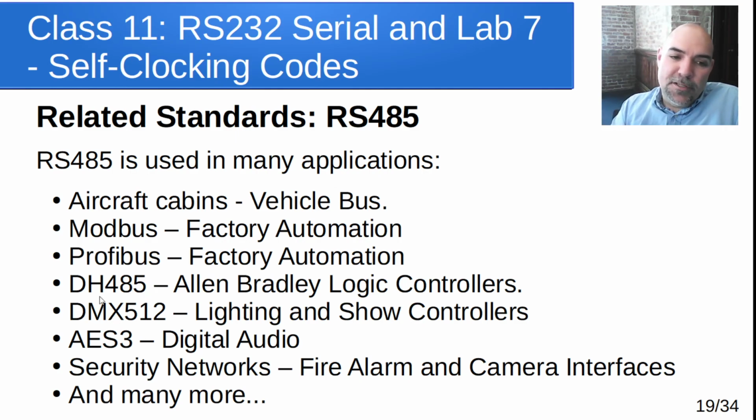So if you can talk in RS485, you could talk to those show control systems and send out the messages to say, set the light color of this light to this, change the position of this thing to this, sweep this one over that way. And there's entire software that drives those kind of concert performances, usually with somebody controlling those things. Dimming values too. Dim this light to half, pointed in this direction. All of that is RS485 that drives that.